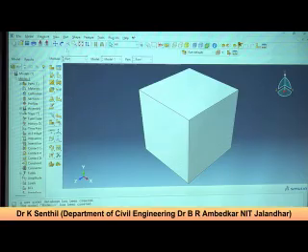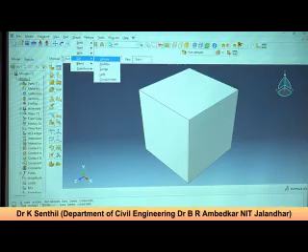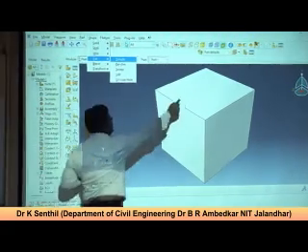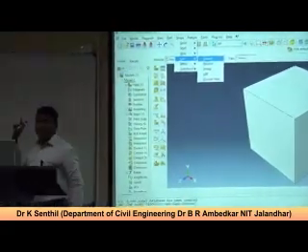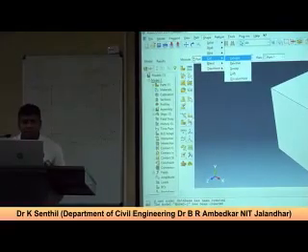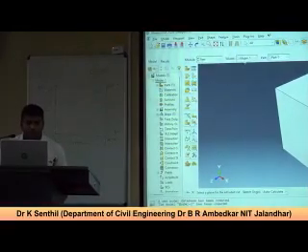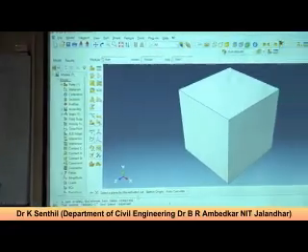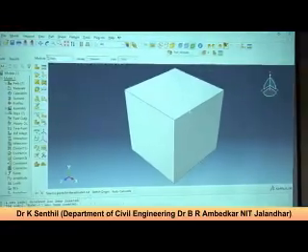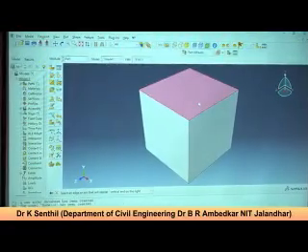In this you can see there is a shapes cut. Okay, and you can say extrude, because you have to cut it, maybe from here. It will go maybe, let's say, 5 meter. The depth of the pile is 5 meter. Now let's go extrude. You read here, select a plane for the extruded cut. So here I am selecting it.